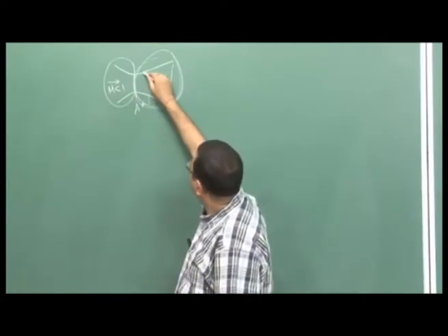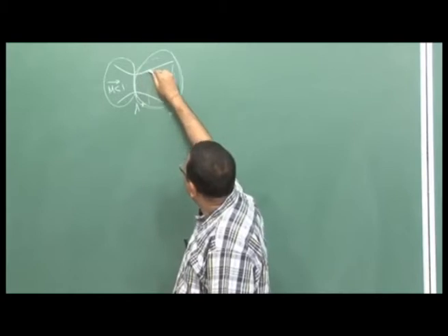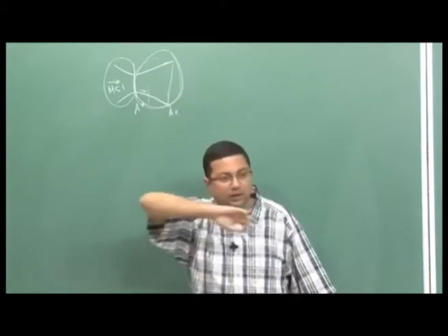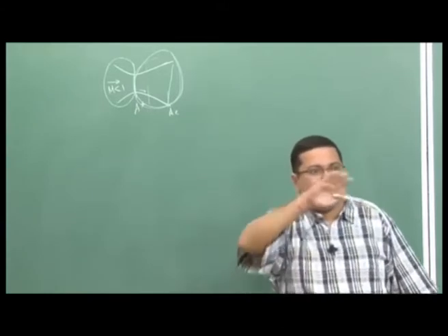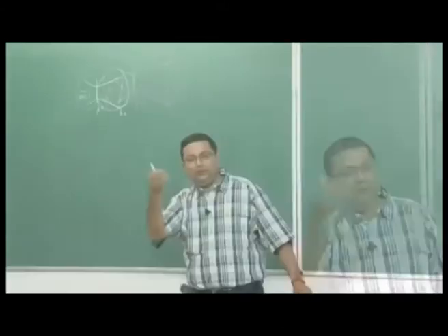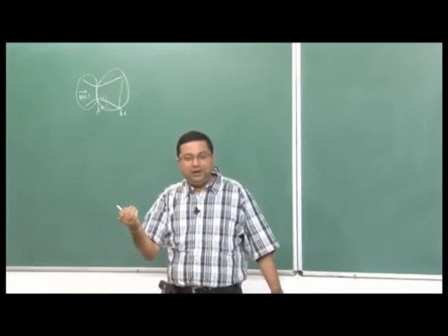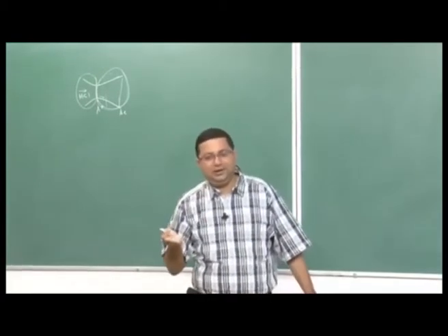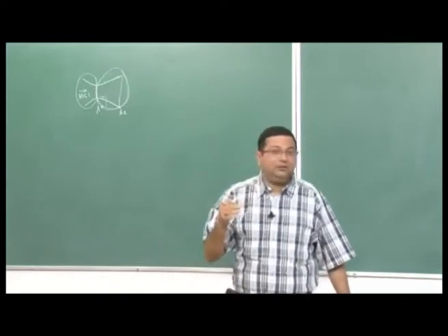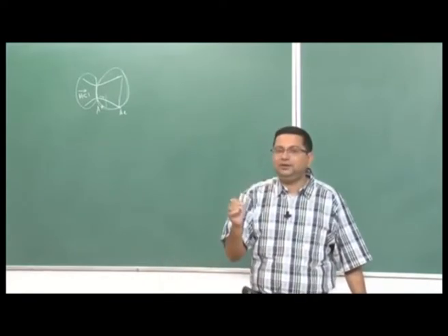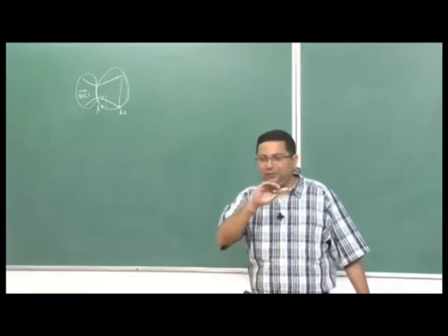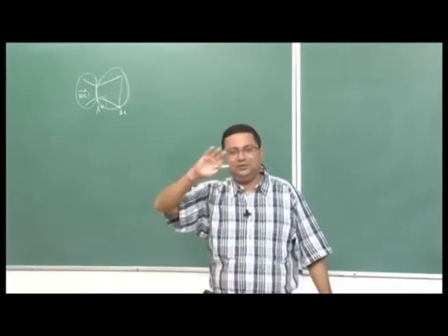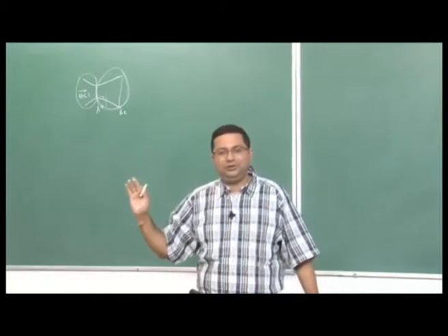On the other hand, if you look at the contour here, it is diverging and the flow is supersonic. When it goes around a curve, the flow will accelerate further, but there will be an expansion fan coming here. We would like to have this expansion fan, because an expansion fan is isentropic. So, we have to design essentially considering a series of expansion fans, which give us the proper contour.